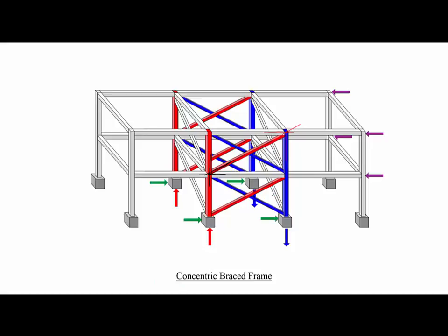Now, as I said, brace frames generally provide large stiffness, but they are not as ductile as other lateral force resisting systems, mainly the moment frame that we are going to talk about. But the main disadvantage of brace frames is that once we put the braces within the area, we cannot put a door or window. Obstruction of space is basically the problem, which is the same problem for shear walls. Shear walls and brace frames have the same problem.